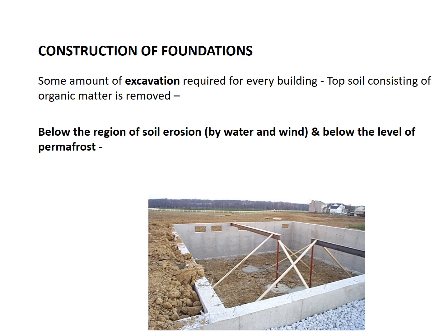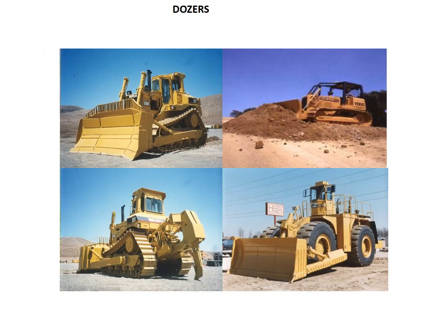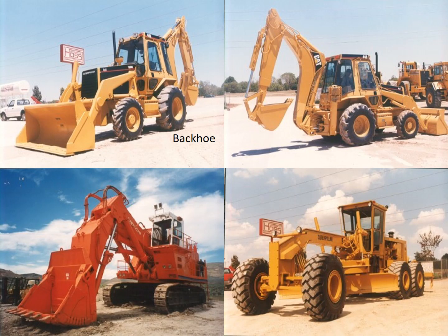There's a whole item about preventing cave-ins by different methodologies called benching and sheeting, for example. Bracing, and the idea of dewatering these types of excavations, getting the water out to keep them stable, using well points and sumps, and sometimes placing watertight barriers to prevent water from seeping into the excavation, and even mixing the soil by rotating paddles. Here are a couple of pictures of the different equipment used in creating the foundation work, and a little bit more on the equipment.